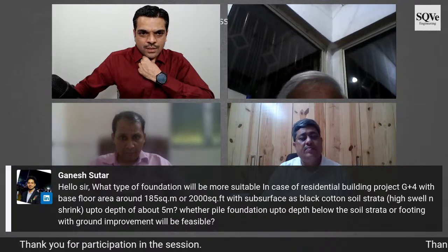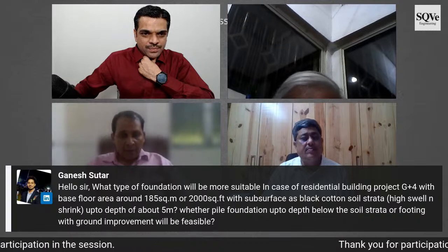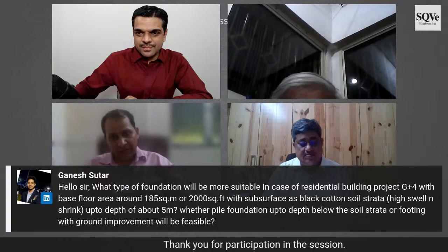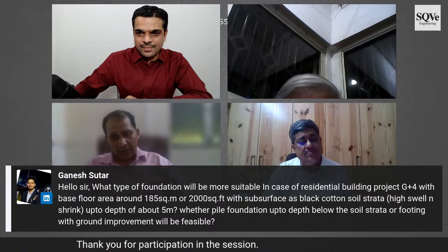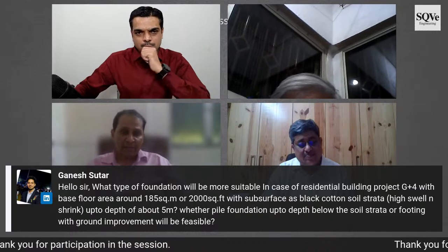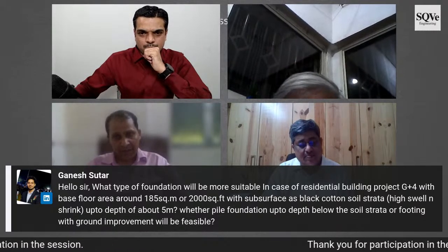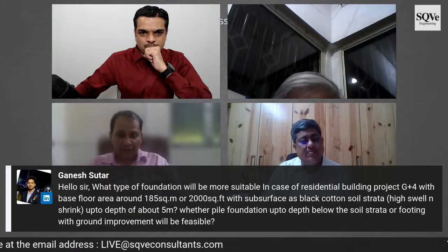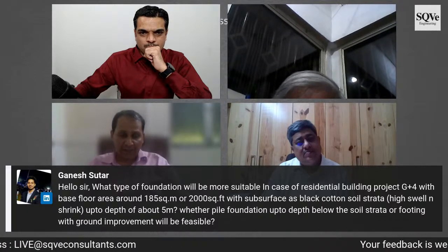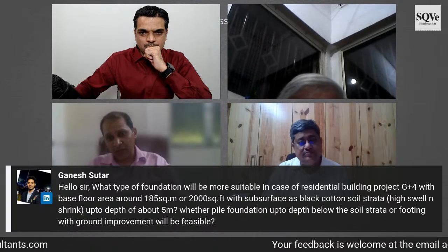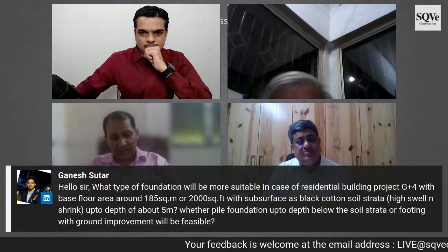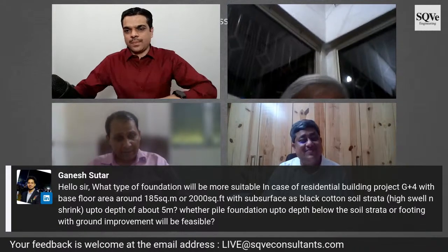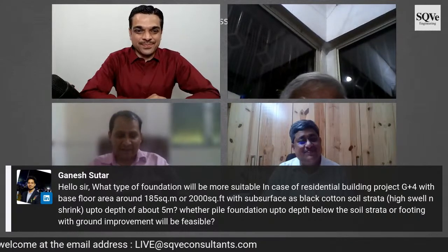Sandeep wanted to say. Yeah, Sandeep ji. Specifically, the question Suhas sir has raised is about understanding how the bulb can be ensured or how can we install the bulb. Bulb is a challenge in itself, because if it's cohesive soil, you can develop the bulb, but in case it's in sandy soil, it cannot. Generating a bulb is a challenge in itself. In that case, you don't require it also. Yeah, to some extent.